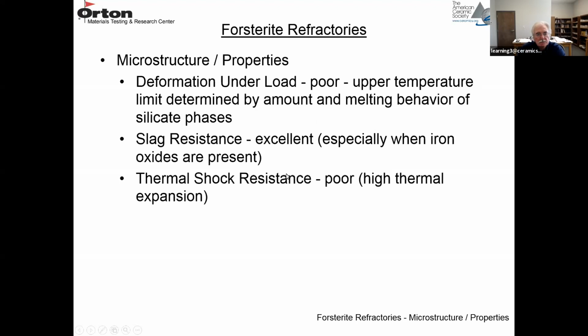So the properties, the deformation under load is not very good for these materials because of the silicate phases that are present. They're going to melt and become less viscous at lower temperatures. So hot strength, creep resistance, not very good. However, they're excellent in slag resistance, especially when iron oxides are present, because they can tolerate iron oxides and not lower the melting point that much.